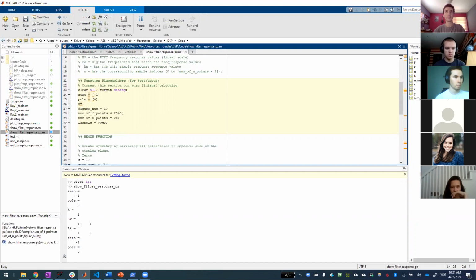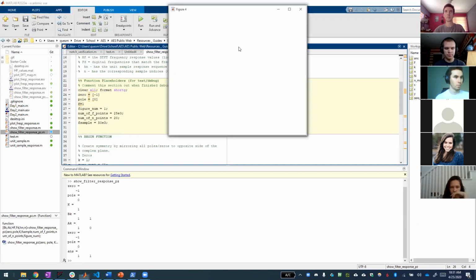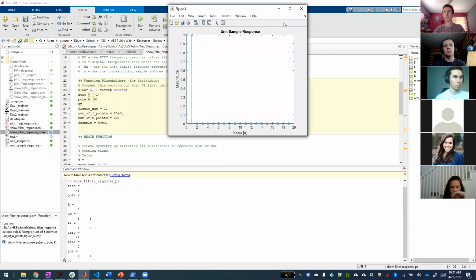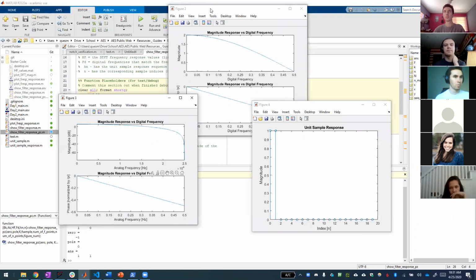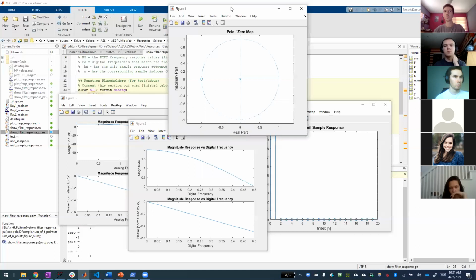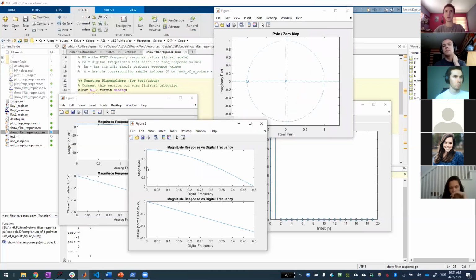If we run this, that's our frequency response. You can see that we would actually need to modify that gain term, because at 0 frequency we're hitting about 2. If you'd want a unity gain low pass, you'd want that to be 1. So you'd mess around with the K, but that's the basic idea: you're starting here, you put a zero here.